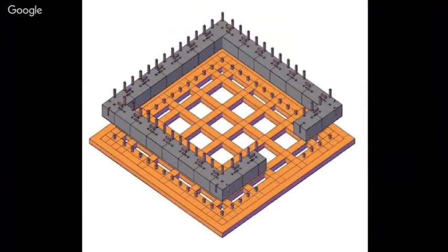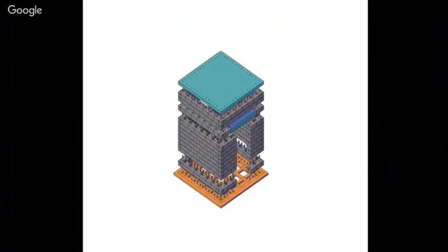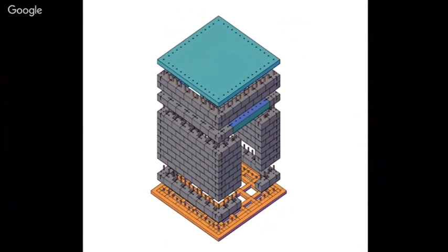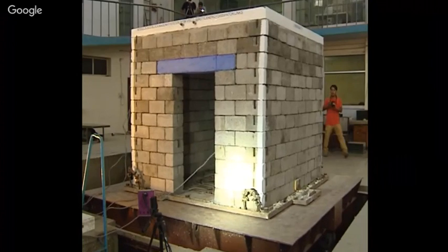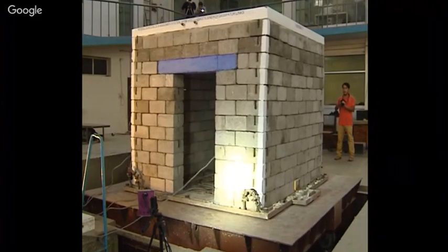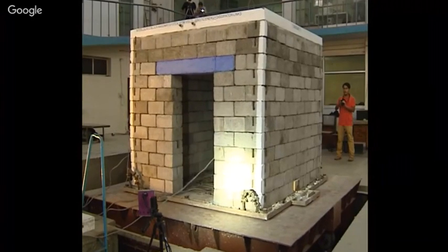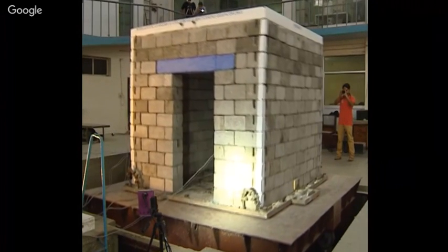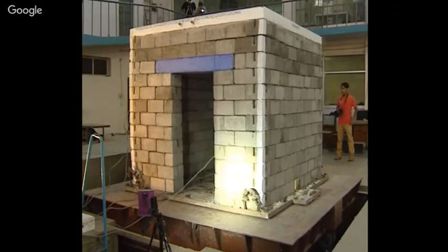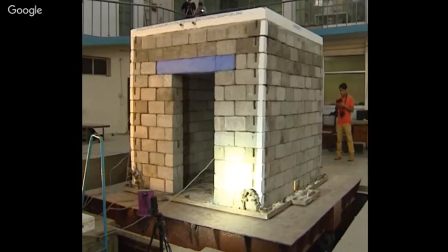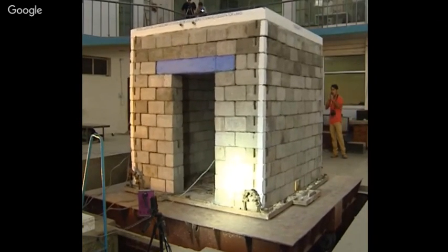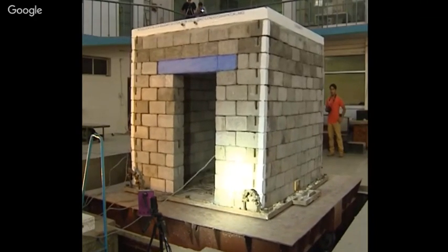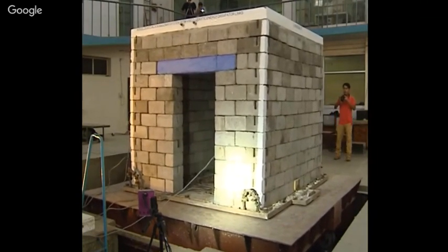Its seismic performance was analyzed experimentally also. A full-scale housing model with maximum load carrying capacity was made on the shake table and tested under a series of simulated earthquake motions. Peak ground acceleration of 0.18 G and 0.36 G, that is, design basis earthquake and maximum considered earthquake of zone 5 respectively, considering soft soil condition, was applied. The experiment was a success. The energy imparted was completely dissipated through friction and viscous damping of viscoelastic links. The model retained its original shape and position after the tests.